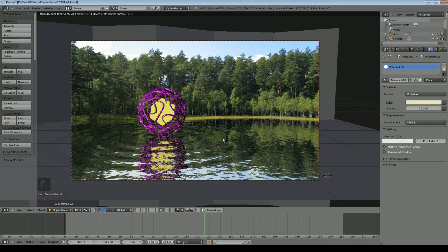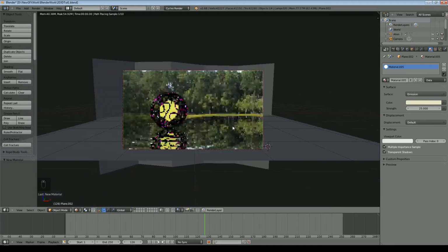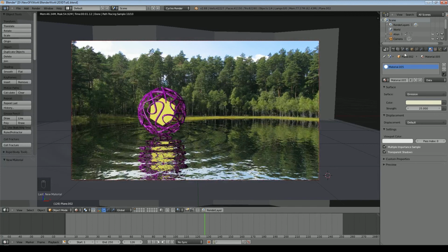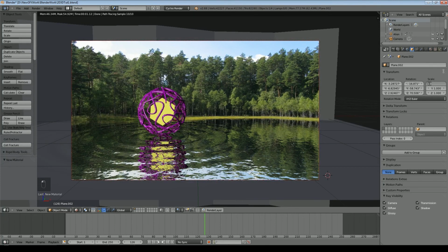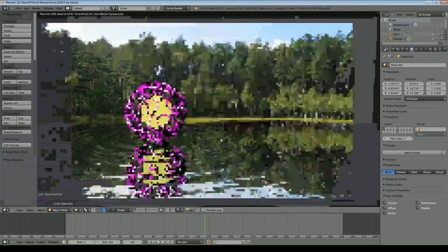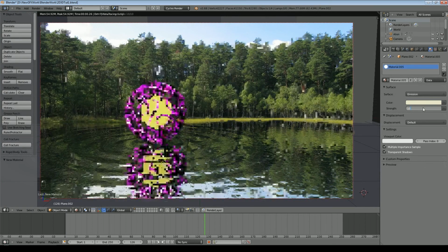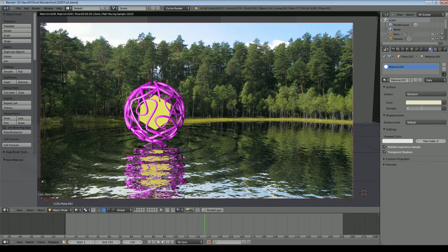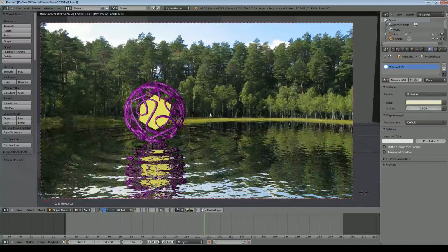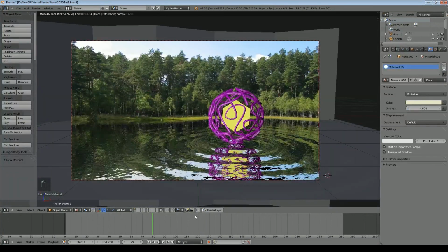Now the sun gives fairly sharp shadows, especially when it's bright like this, but in this scene they're not that sharp. So what I'm going to do is come over to scale, and I'm going to say 3 for the scale. Now that's also made it a lot brighter. That's just the way that Cycles works with emission shaders. So we'll set this down to 10, perhaps even lower than that, 5. So now you can see that they're much softer shadows, and you just have to play with this. I'm changing it down a little bit further, maybe 4, to get something which you think is a reasonably convincing level of light, and obviously play around with the position of it.